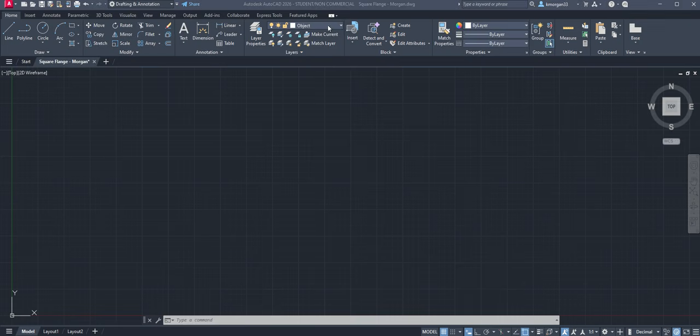It means that out of all the layers, we are going to draw the object on this object layer. And then now we will go into the draw panel. In the draw panel, you're going to choose the rectangle, polygon drop down menu, and we are going to choose a rectangle. So here we have line, polyline, circle, arc, rectangle, and polygon is right here.